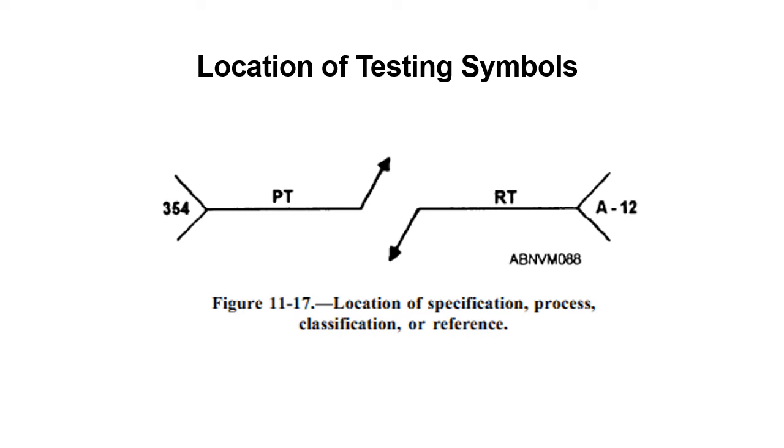In my experience, a lot of designers are reluctant to do this, and I don't know why. I think it's because they think, well, I've got an NDE or a welding symbol, and the welder should just be able to know exactly from that one symbol. Well, sometimes things are a little more complicated than that. Anyways, don't be afraid to let people know that they can use the tail to put supplementary information in there.